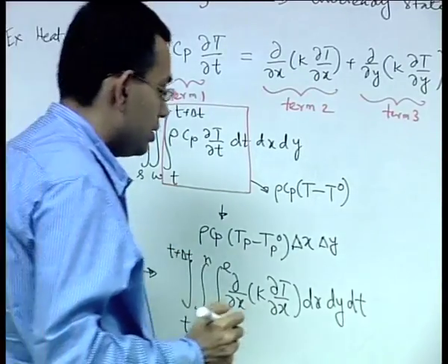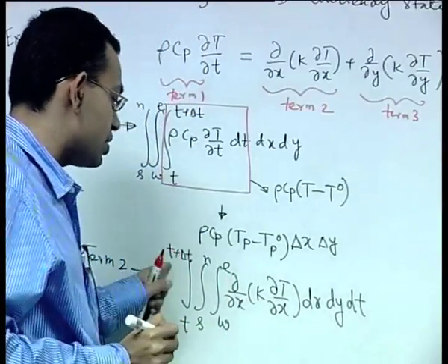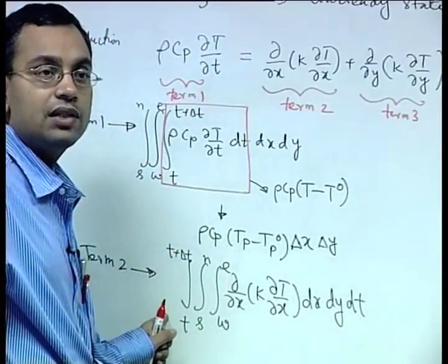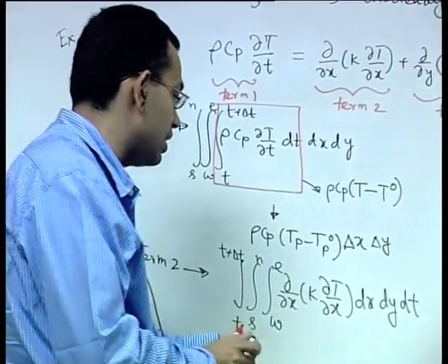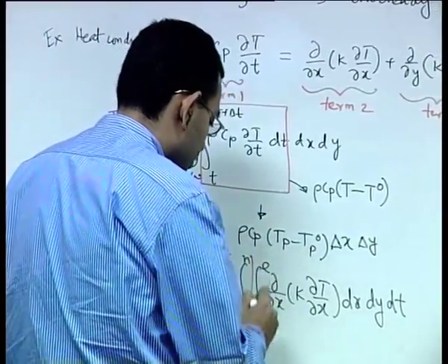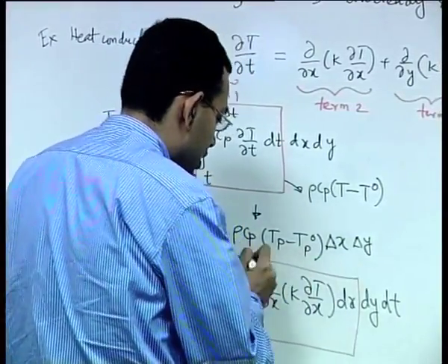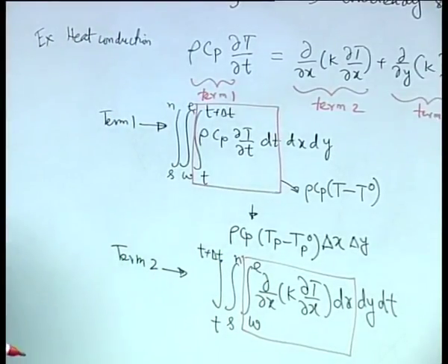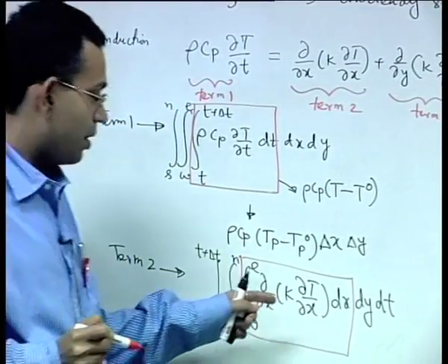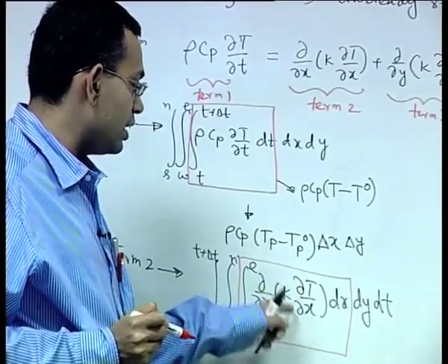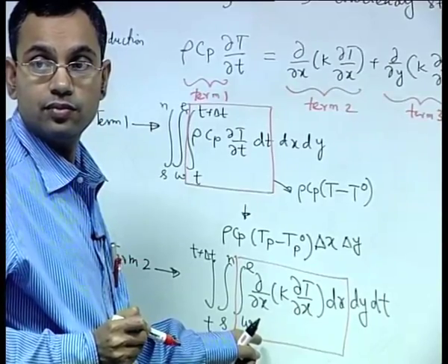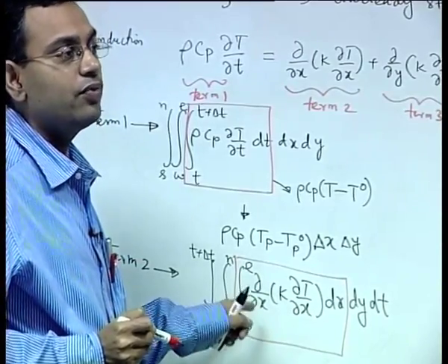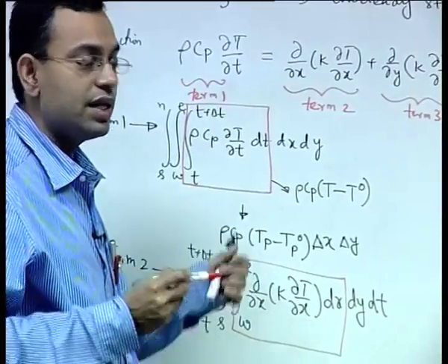Now this of course depends on what is the time integration scheme that we are using, but before that let us consider the spatial integration. So first this integral, so it will become k del T del x at small e minus k del T del x at small w, right. What kind of profile you can take? Piecewise linear.